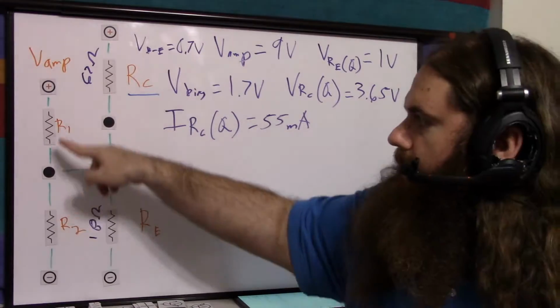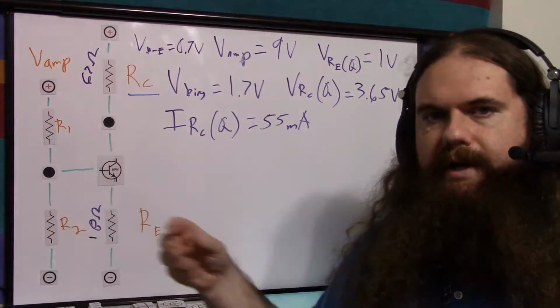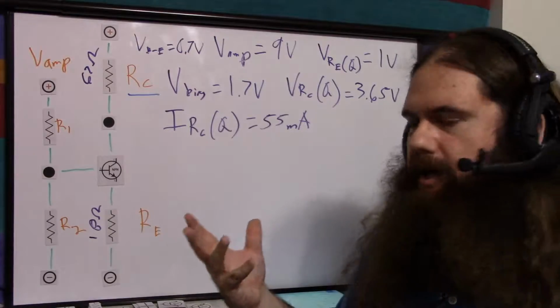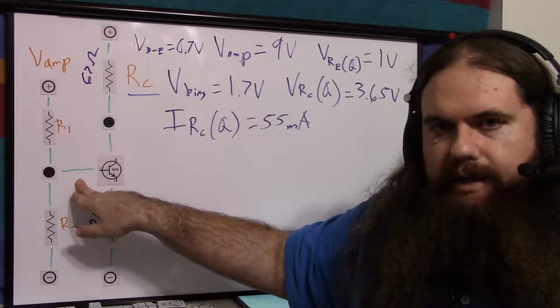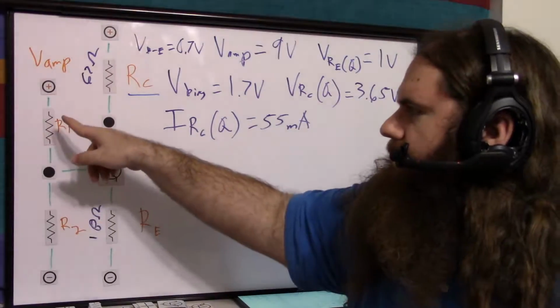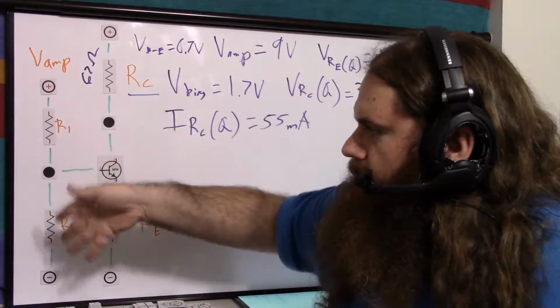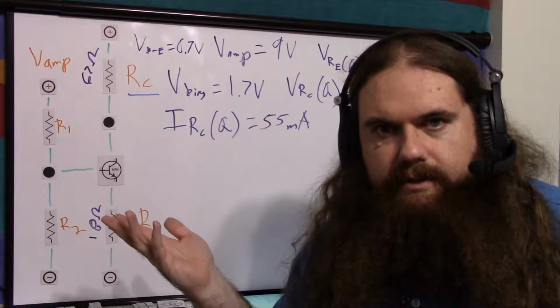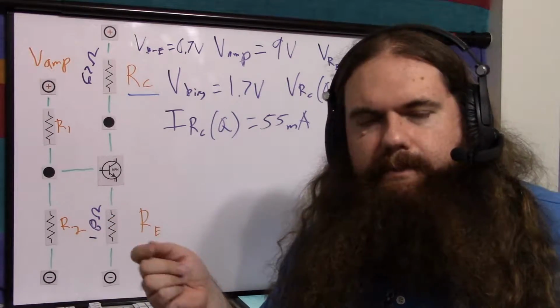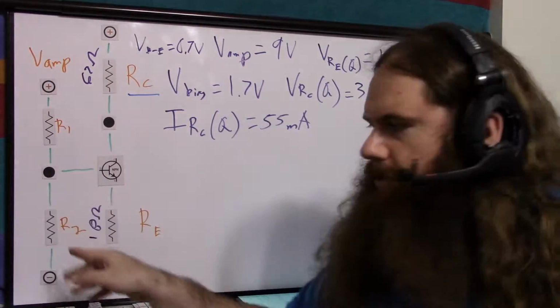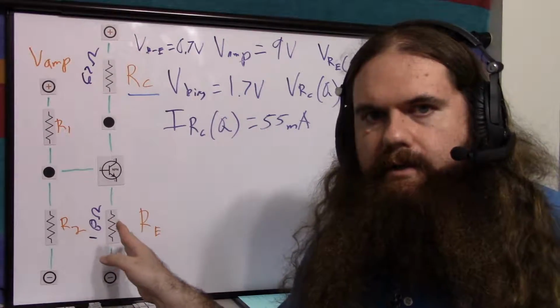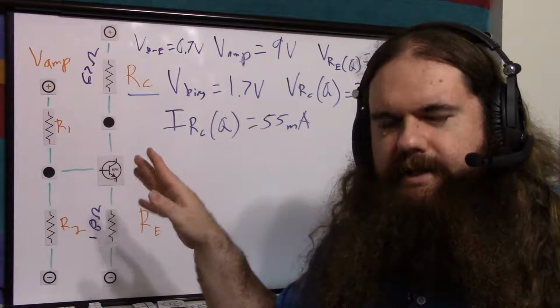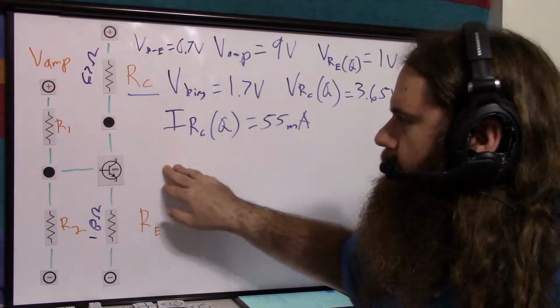Recall where I said that we want this to be providing at minimum 10 times the base current we need at quiescence, and more is better. So basically this is a waste. It's always putting power through. But by having that headroom, and times 10 is just a rule of thumb, somewhat random, just more is better. This helps with your stabilization of the emitter resistor, to make sure it always can take or not take what it needs. So you just do the same thing.